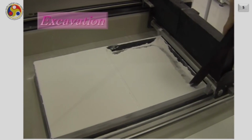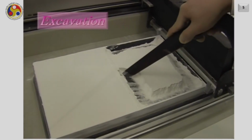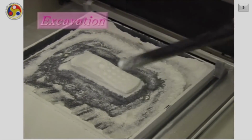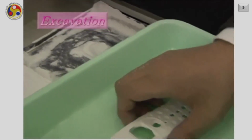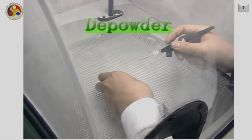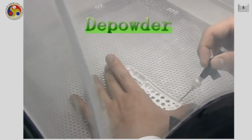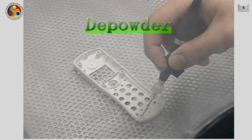Here in this case, the loose powder itself acts as a support material. There is no need to generate any external support in this process. So this is the green state part, and carefully it is removed from the powder bed. Then the loose powder which is acting as a support material in the overhanging zone is carefully removed by compressed air.